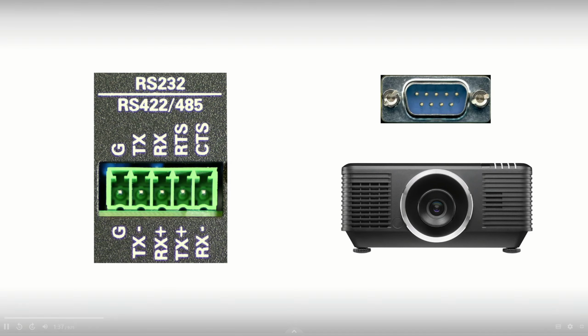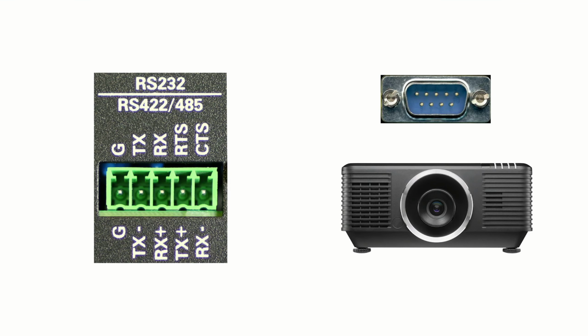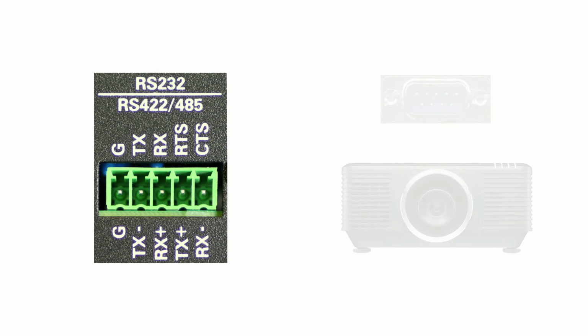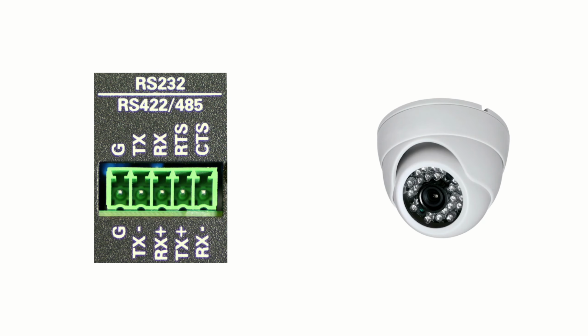RS-232 is the most common protocol. Any device with a COM port supports the common RS-232 protocol. Some ports also support the RS-422 standard. This is less common, but still in use because RS-422 is a balanced communication that offers a greater distance over the RS-232 protocol.